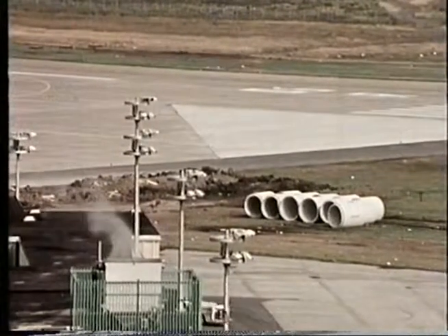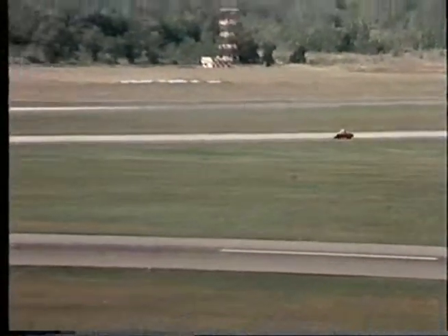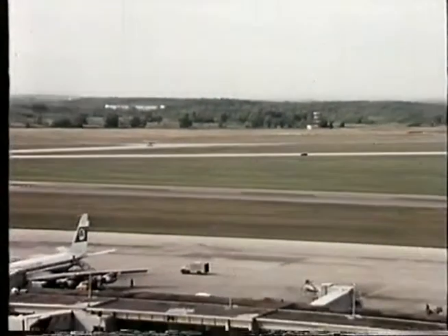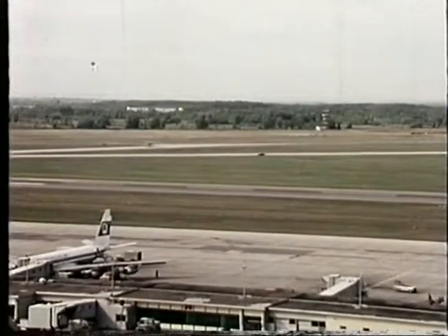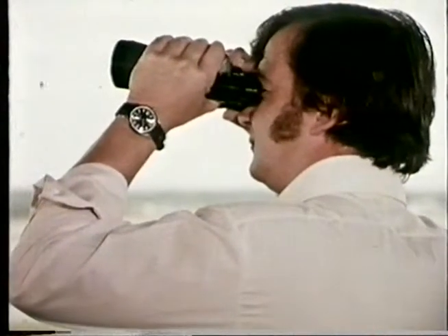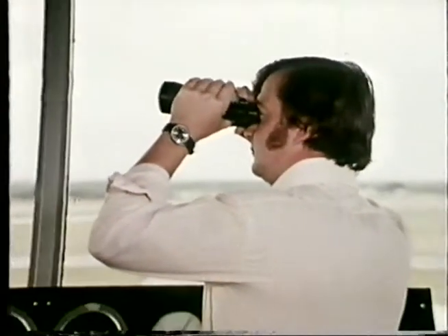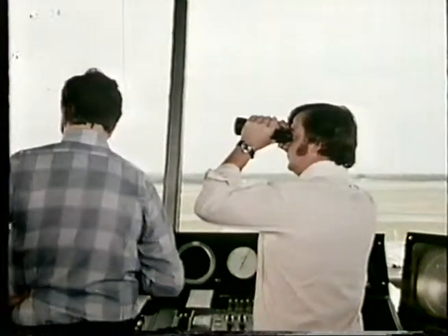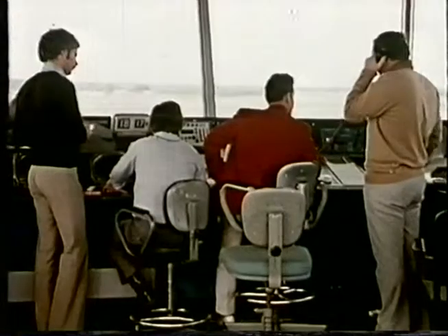It will be seen that in order to provide separation of airdrome traffic, the airdrome controller must maintain a continuous watch on all airdrome traffic, both in the traffic circuit and on the maneuvering area of the airdrome. Remember, this includes vehicles and personnel, particularly on the taxiway areas.